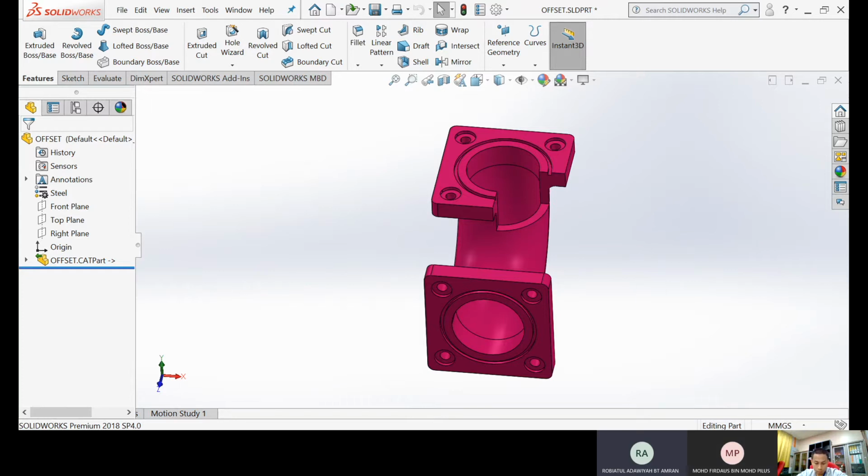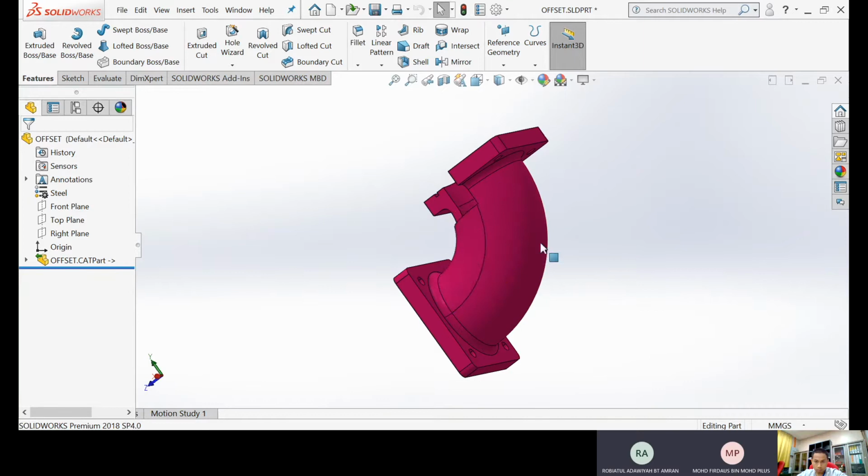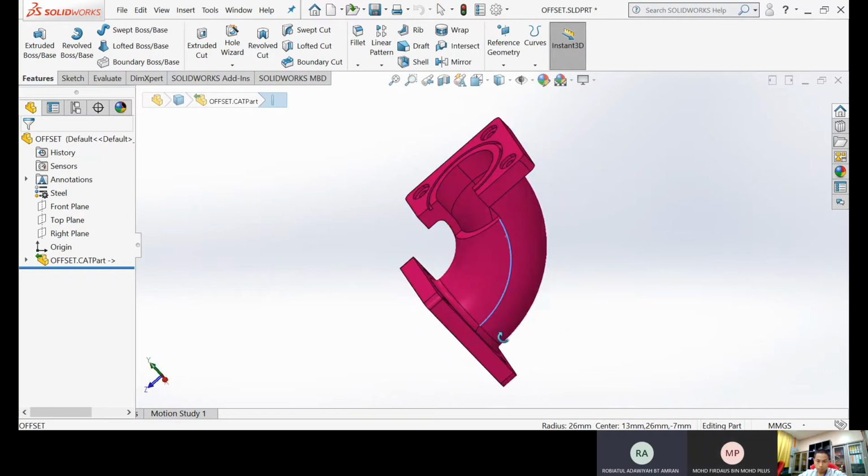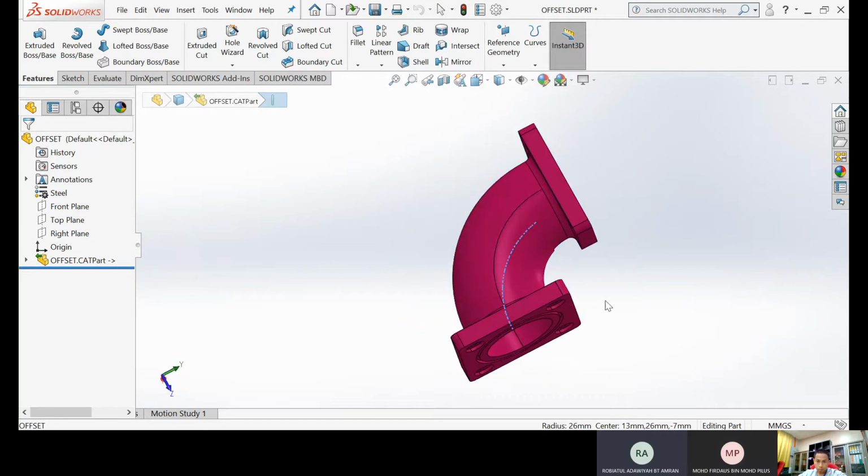Next, part 3, the curve wizard. The curve creates boundary and section curves in point cloud and STL files. Select a pair of points, a plane, or an existing curve. Use reverse direction if necessary to switch the direction in which the section curves are created. Selecting a pair of points defines a vector. The software creates intermediate section planes perpendicular to the vector, starting from the selected point on the start plane.